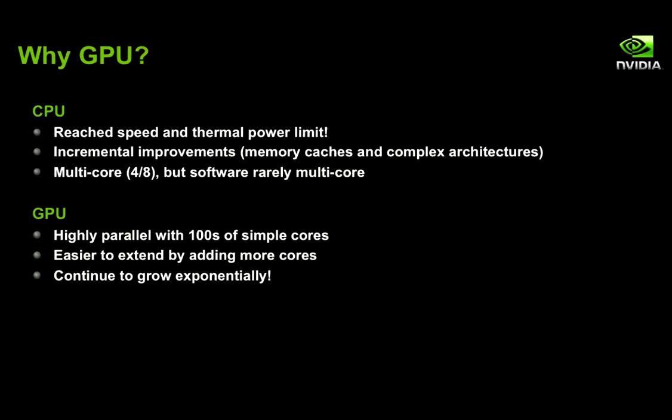The other major thing that's happening in the CPU world is the introduction of multiple cores. However, when you do introduce multiple cores, there's often the burden that software programmers have to explicitly write their code to make use of these multiple cores using multi-threading, TBB, or pthreads, or any kind of threading software libraries. However, this is quite burdensome, and not a lot of software code exists that's actually multi-core.